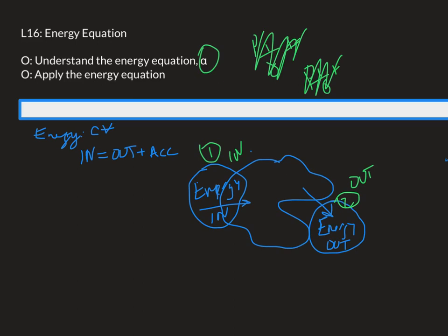There are ways to add to that energy, and one is you can do work on the fluid. If you want to do physical work on the fluid, one of the things we'll use is a pump. You can imagine how, if you add a pump, you can add potential energy by pumping something up a hill. You can add potential energy by increasing its pressure. You could add kinetic energy by making it flow faster. Generally speaking, pumps add pressure is really what they do.